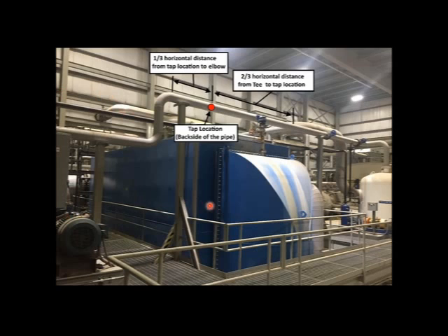Here's the unit. It's a small combined cycle unit. The steam comes in from the side of the condenser. There's only one inlet water box, one outlet water box. This is their vacuum line. They have installed ball valves in the vacuum line. So we came on site with a rental Reovac, installed it in the line, got some measurements, and measured the vacuum pump capacity. Let's take a look at the data.